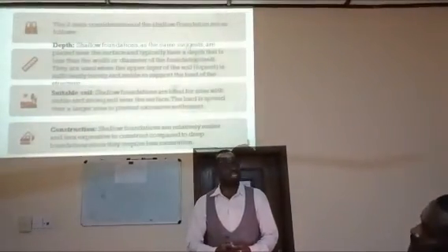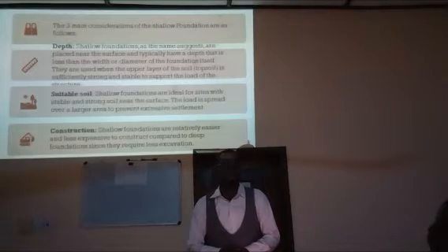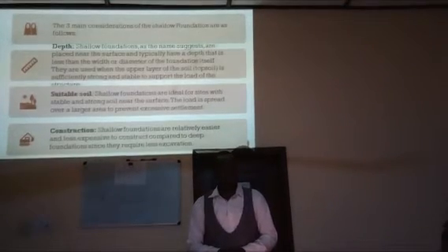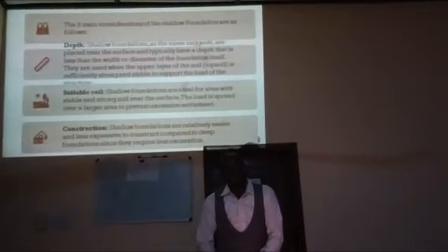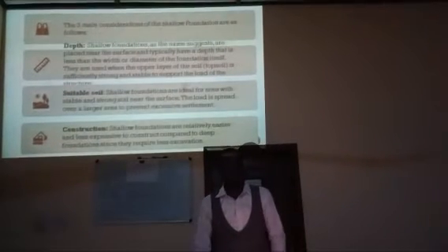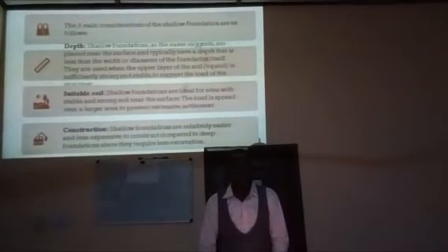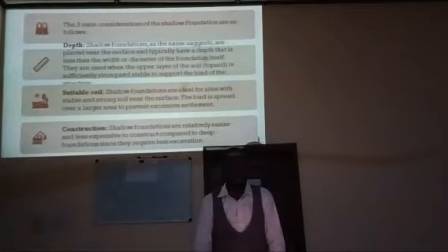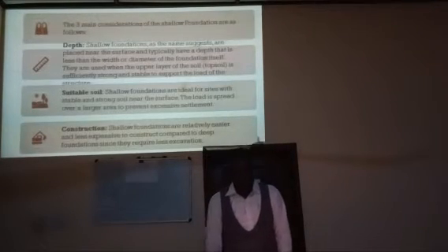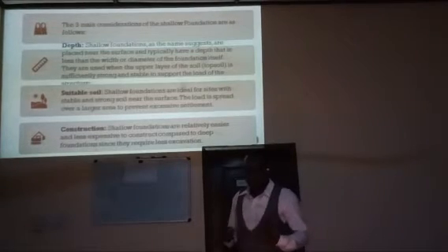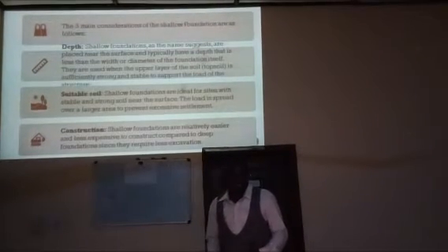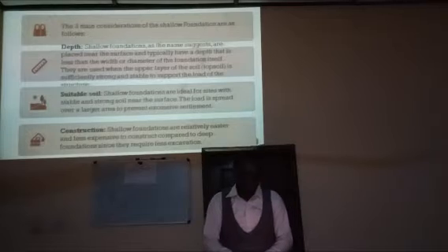In order for us to decide, okay, we want to use shallow foundation, we should be able to make sure that the soil can carry the foundation so that there will be no settlement on the soil, or external factors, erosion and all, cannot affect the soil at a much later time. Okay, so once we have been able to convince ourselves in that regard, then we can go ahead and build it as a shallow